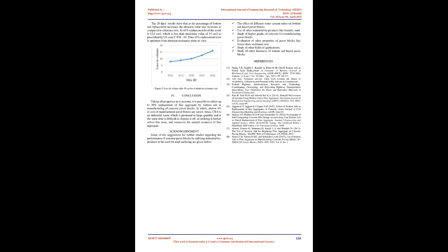But up to 30% replacement, it complies with the requirements of the code. Hence 30% substitution level of CBA is the optimum. However, it fulfills the minimum requirement of 35 MPa at 45% replacement level at 28 days also. Figure 2, variation of compressive strength with age for various mixes.